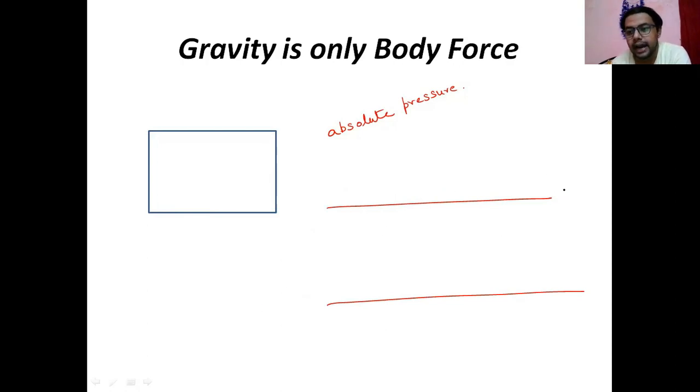Reference, this is the atmospheric line. Atmospheric pressure is at here. This is the reference line. So from here you're considering atmospheric pressure is PA. There is some value, 1.013 into 10 to the power 5 Newton per meter square. Don't confuse with this. That means 1 bar or 1 atmospheric pressure. So atmospheric pressure sometimes we are taking as the reference.